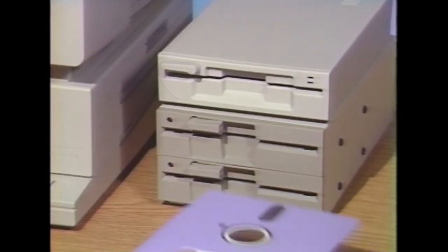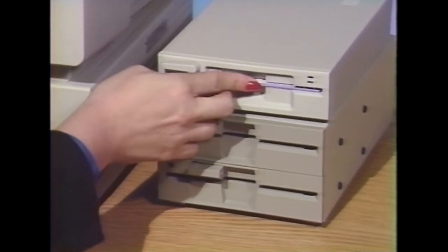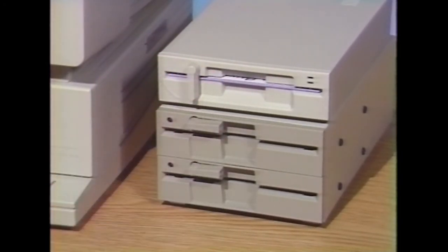Place your backup copy of the front side of PC Transporter's boot disk in the Apple's boot drive. This is the drive connected directly to the Apple, not to the transporter. It can be either a 5 1/4 inch Apple compatible drive or a 3 1/2 inch Apple compatible drive. Place your backup copy of a bootable MS-DOS system disk in the PC Transporter A drive. This is usually the first drive in the disk drive daisy chain. You can use the trans drive shown here or an Apple 3.5 drive.